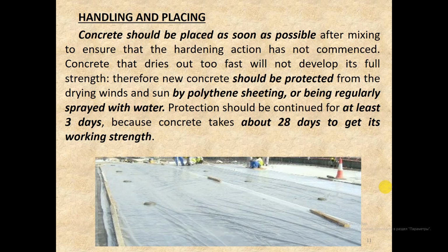Therefore, new concrete should be protected from drying winds and sun by polyethylene sheeting or by being regularly sprayed with water. Protection should be continued for at least 3 days because concrete takes about 28 days to get its working strength.